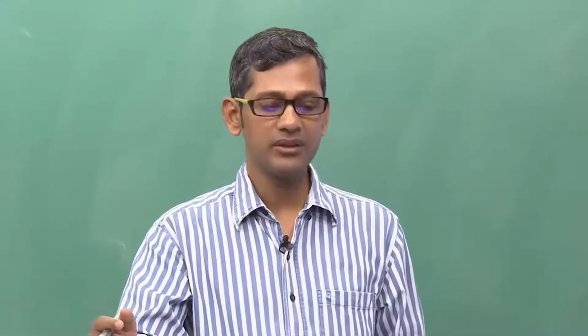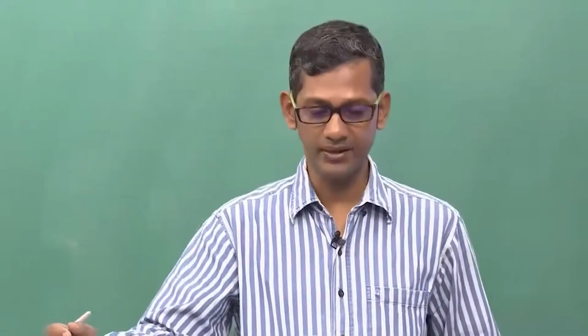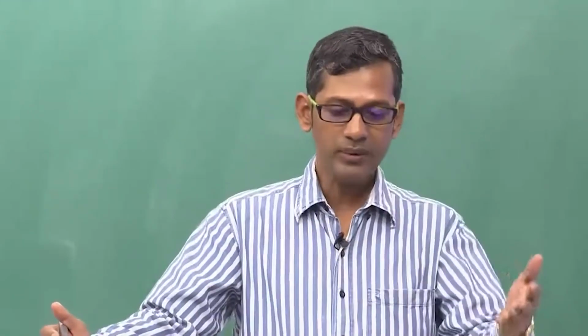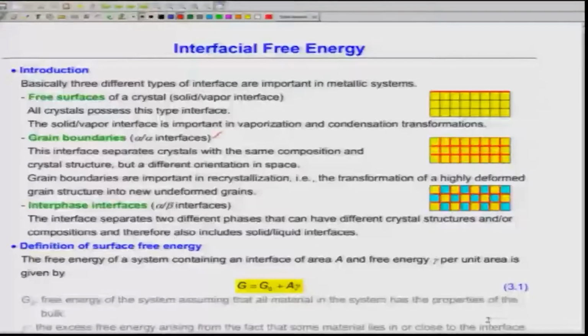Whatever the situation, you have to deal with interfacial energy. So whether it is a solid vapor interface, an alpha alpha interface, or an alpha beta interface, we are going to deal with boundaries, and boundaries will have energy, and this energy is always defined as interfacial free energy.